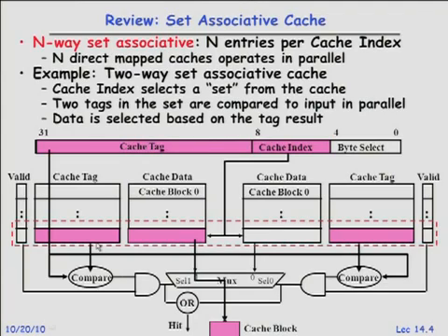Okay. So now, by the way, you can see where conflict misses come from, because in this arrangement, if you can have 2 addresses that have the same index but are different because the tags are different, those 2 addresses have 2 places to sit, right? They could be here or here, and so that uses up those 2 places. If you have a third address that has the same index, now you got a conflict. Even though the cache is not full, you're conflicting on that one set. Okay? Good. Fully associative cache. Basically, you throw out this whole indexing idea. It goes to 0, and you have a single bank with everybody's got a tag and everybody's got a comparator, and you compare in parallel everybody, and you find one that matches. That's fully associative.